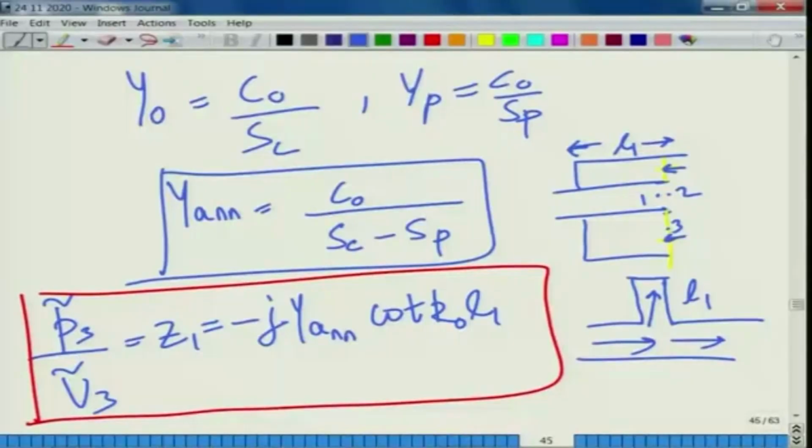And it turns out in this case it is going to significantly not only kill that particular trough or that problematic frequency, it is overall going to improve the transmission loss performance in the vicinity of such a problematic frequency.